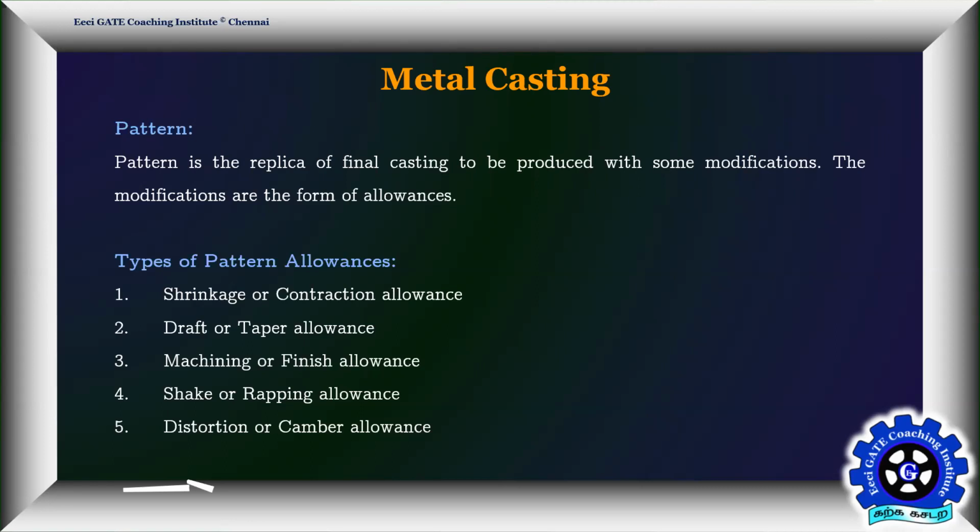So what is pattern? Here you can see pattern is the replica of. What do you mean by replica? Replica is almost exactly the same, a copy. So pattern is a copy of the final casting to be produced, with some modifications. Those modifications are in the form of allowances.